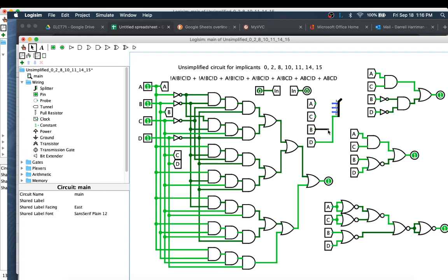And that's not what I wanted. So I select the corner of the wire, right, and hit the delete key. And that deletes that section from going both ways from the corner. So there are some wiring tricks you'll get used to.